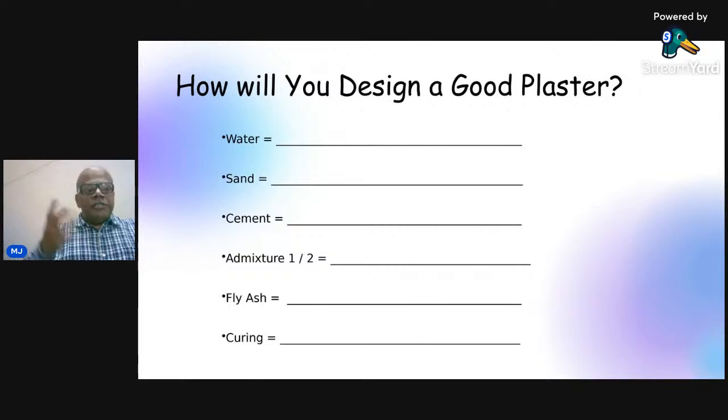So normally we all engineers go to site and we feel that 1:4 plaster is better than 1:6 plaster. Is this a right statement? Because the number one enemy for our plaster is shrinkage. We don't want strength in our plaster. Strength we want, but just enough that it will hold in place. We don't want it to shrink. We don't want it to crack. So, do you want more aggregates or lower aggregates? Okay, higher, higher, higher. So, higher what? For water or for sand? Mr. Mohammed, your answer you are giving, higher is for water or is it for sand?